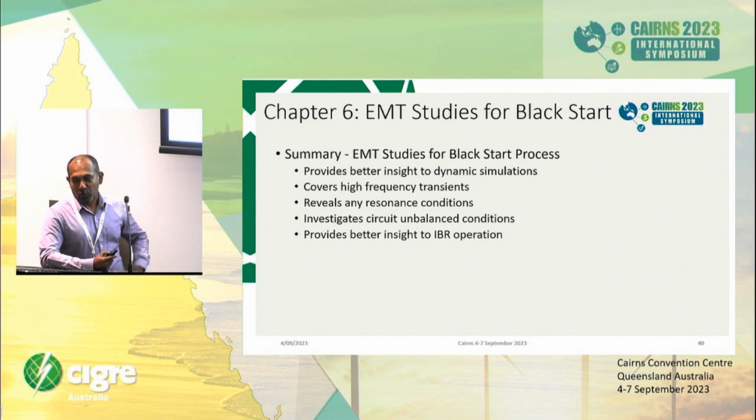It will cover the high frequency transients, and also it will reveal any resonance conditions, due to induced voltages. And obviously when it comes to unbalanced situations like unbalanced faults, EMT would be a good software to simulate. And black start is a condition you can consider as a low short circuit ratio condition, and once you bring IBRs into the system, it is better to do some kind of EMT studies, especially since even grid-following inverters highly rely on a sinusoidal waveform.